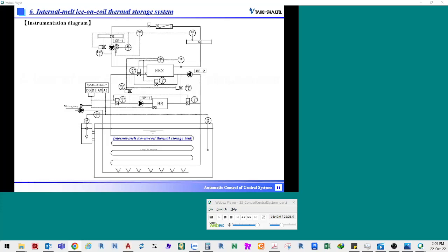In the room, the body temperature is higher than the room temperature, so the heat generated by a person also acts as a heat load. In addition, heat is generated by lighting equipment, and air coming in through the gaps in the sash of the window and the door at the entrance may also cause loads.